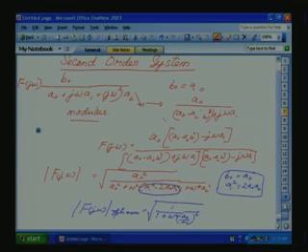So by choosing these parameters, this second order system we can optimize so that for a wide frequency range we get a modulus of 1. That is, for any frequency variation of input, the output will closely track the input. So this is one way.